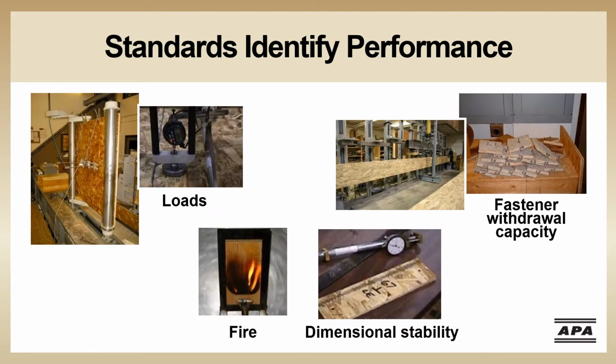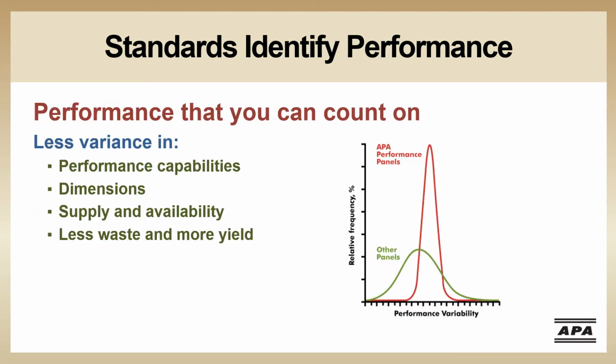We don't have time today to review all of the different tests that PS1 and PS2 wood structural panels are subjected to, but they do include bending, impact resistance, fire, dimensional stability, and fastener withdrawal capacity. Because of the PS1 and PS2 standards, the reliability in performance and dimensional sizes are much greater than those products that are not manufactured to standards.